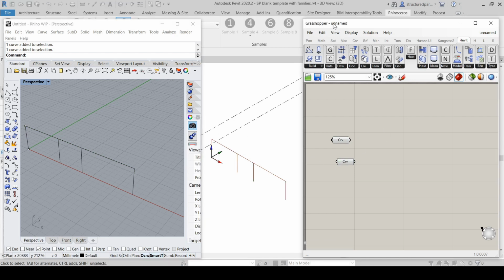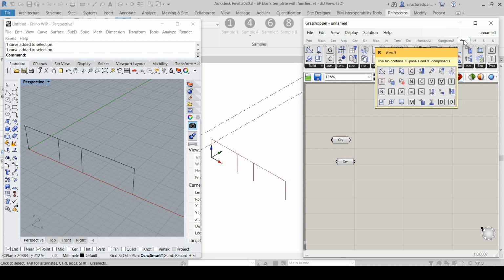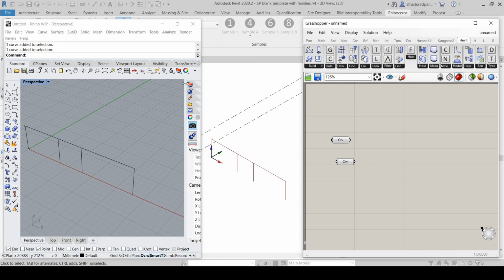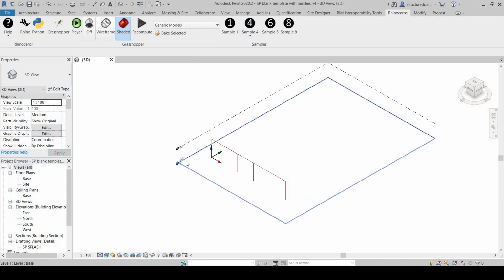Okay, so under Grasshopper, you'll have a new tab as well called Revit. To create some beams in Revit from your lines, you just need this component, which is Add Beam by Curve. Pretty simple. This needs a curve, a type, and a level. The level's pretty easy. If you go to Document, and then you've got Document.levels, if you put that in, that just grabs whatever's in Revit at the time. So I've obviously got 2 levels already set up, but that's pretty easy to do.